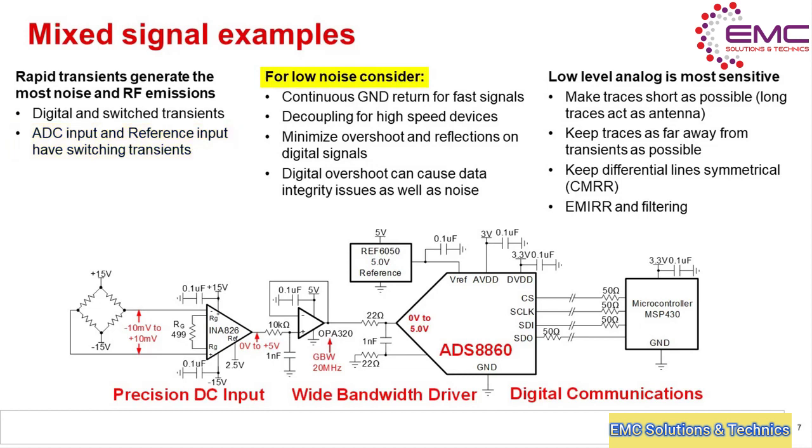There are many techniques that can be used to minimize noise. For example, taking care to make sure that the ground return path is continuous is very important. Proper layout and selection of decoupling capacitors is also useful for minimizing noise. From a digital perspective, minimizing overshoot and reflections reduces noise and crosstalk.